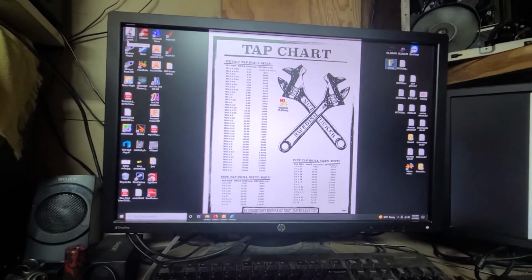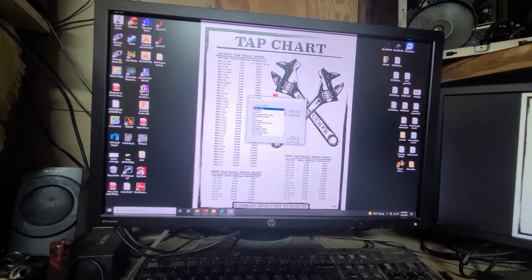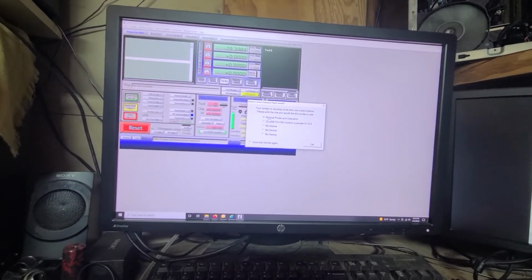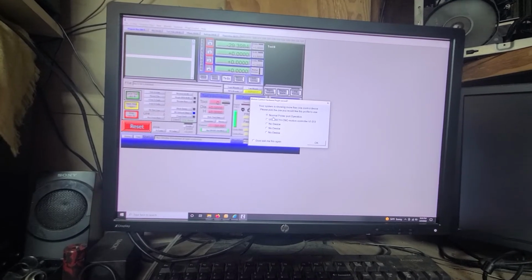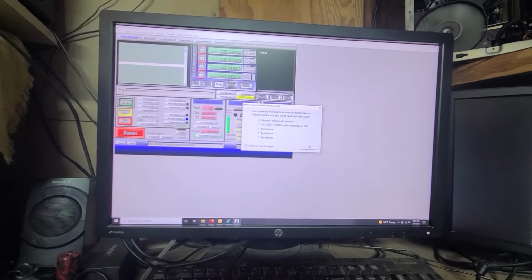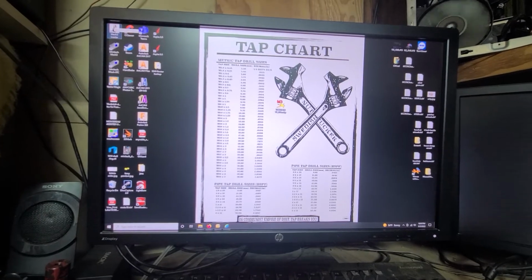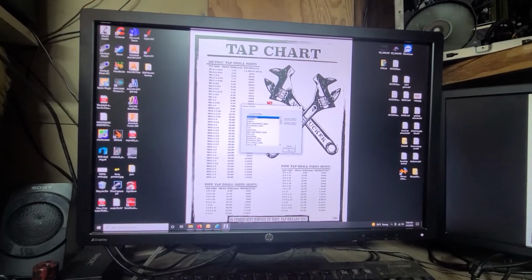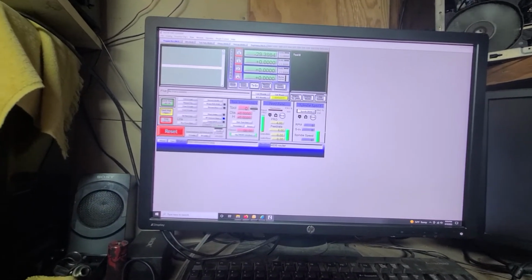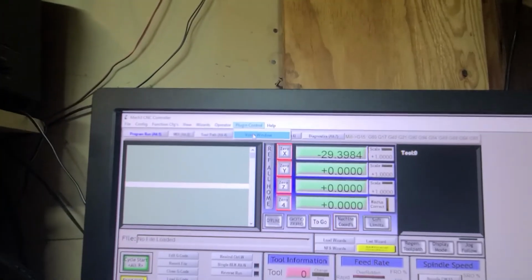So you get the file installed, but when you go and open Mach3, and I'm just going to use this 4030 router profile, this one actually popped up saying you have a motion controller, but if we choose normal printer port, click that, click OK. Nine times out of 10, when you're at your machine, you're going to open your Mach3 and you don't get that box that pops up. And if you come up here to plugin control, you can see all we have is video window.